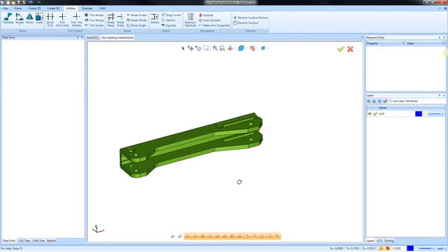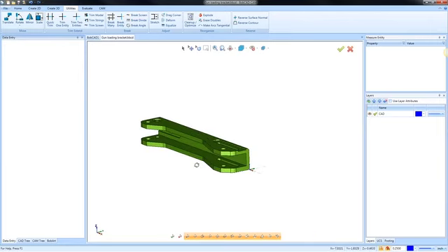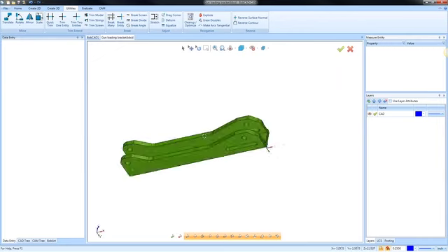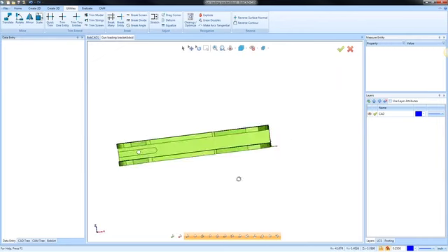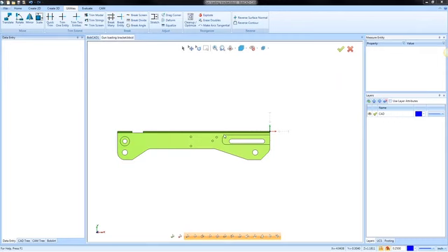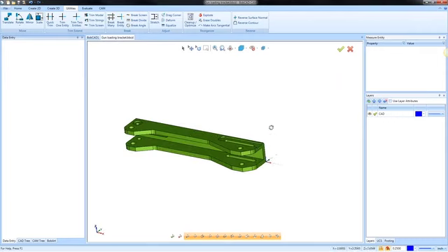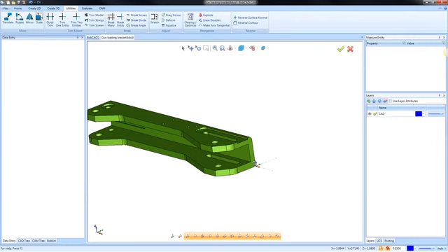Travis says, personal preference, but I find it safer to have top at 0. Okay. Yeah, generally, one of the reasons why I would want to move the top of the part to 0 has to do with when you're creating wireframe geometry. John's also talking about multiple UCSs. This part would definitely have more than one setup. We have a couple of different sides here, so sometimes it helps to have the part geometry located at Z0.